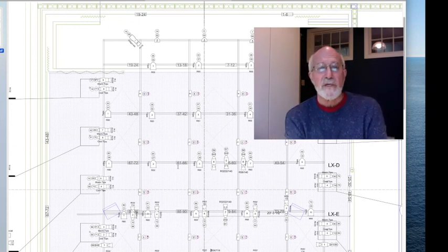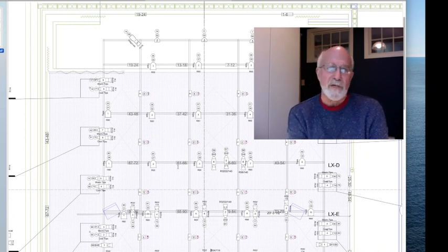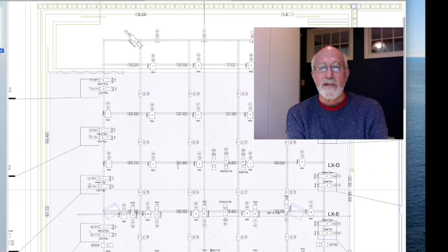lighting circuits. Very typically, the circuits and dimmers would not be identified on the drawing usually, because it's a waste of effort usually, because typically you just go, okay, the closest box to me is 7 through 12, and somebody using highly sophisticated technology, namely a list of numbers from 1 to 96, would say, okay, the only ones not already crossed off and therefore in use, can you plug into 11?